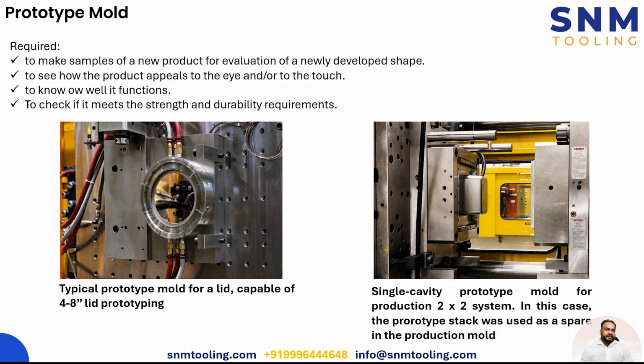And then, for example, if there are threaded components, internal or external threads, instead of cutting out or adding a permanent insert, we can use a loosened insert. Then that can be ejected, and manually it can be unscrewed by hand, right? And then the side walls of the product can just be made using loosened inserts rather than your side cores.